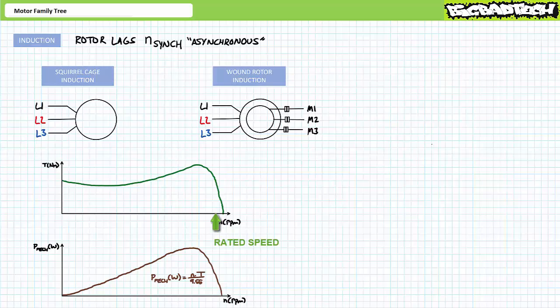3. The rated speed. This is the speed of the rotor when it exerts the rated torque and produces the rated power. This is the data you would see on a motor nameplate because it's normally the most efficient means of operating this particular motor, or nearly so. Anything to the right of the rated condition is an underloaded condition, and theoretically, the motor can operate indefinitely at or under the rated condition. In contrast, anything to the left of the rated condition is an overload condition and isn't meant to be sustained for any length of time. Motors are customarily operated at or near the rated condition. Given the rotor increasingly lags the synchronous speed, this is an occasion of increased slip.